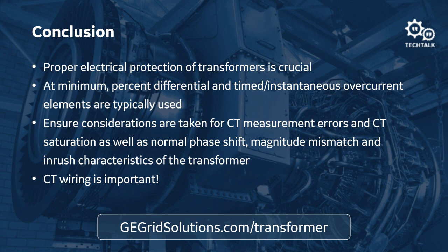Typically, you have to have somebody go out to it and pull the information from it unless you have it networked. What we added in the 845 relay is that you can, via the network, pull that dissolved gas analysis information from that separate DGA device and have a report print from it in the 845 relay. So instead of having to go pull two devices, you can just look at the 845 and get all that information there.